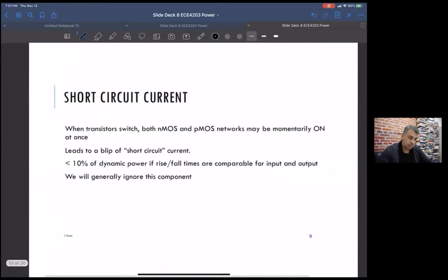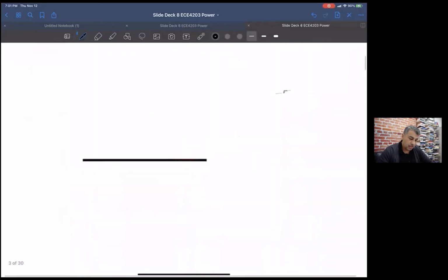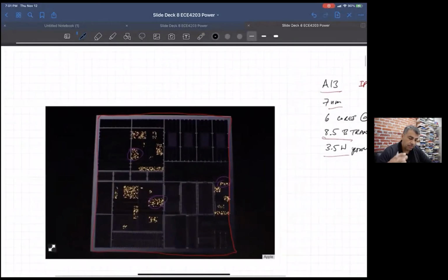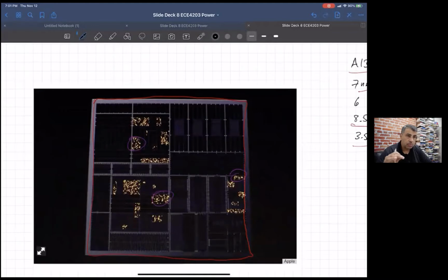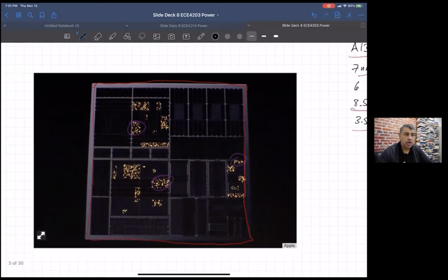So just to go very far back, the main thing you want to do with power, reducing your power consumption or keeping it reasonable, is to have as few circuits as possible operating at any given time. Because as soon as your circuits start switching, they start taking up dynamic power, and you want to keep that only where needed. You don't want any unnecessary switching. So that gives you your dynamic power consumption.